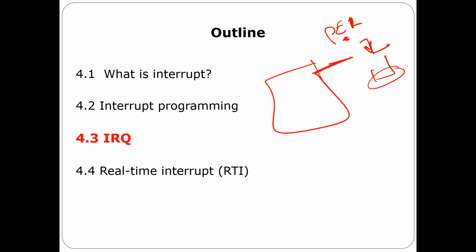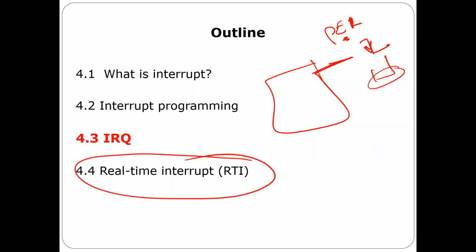As I told you, this falling edge can come from a sensor. Tomorrow in the lab it is going to come from a switch. Today I'm going to teach a different type of interrupt. This one is called RTI, or timer. The main difference between these two is that they are completely different. In RTI, there is no external pin. This one is a timer.